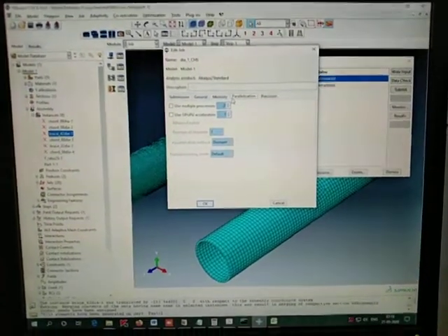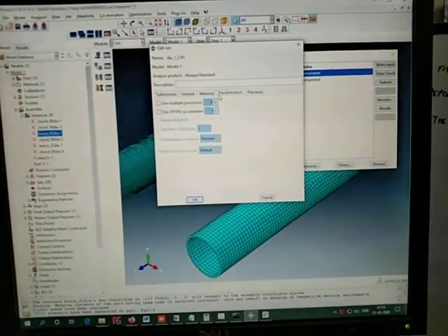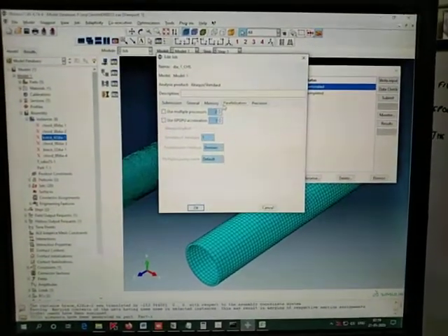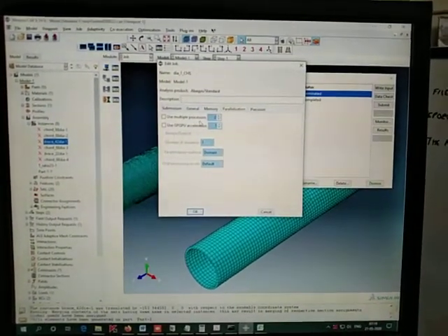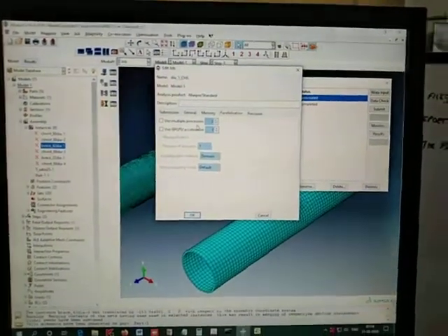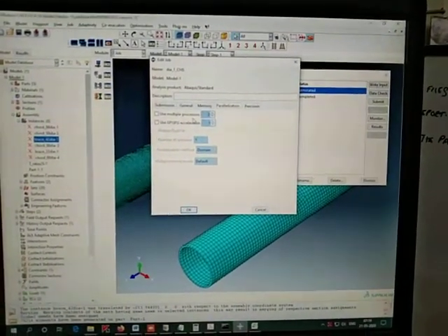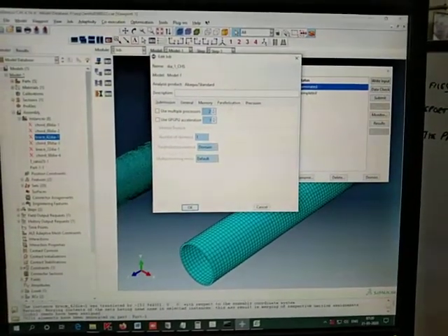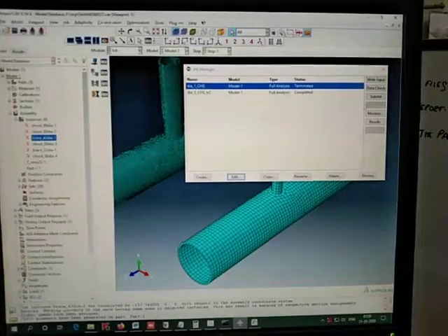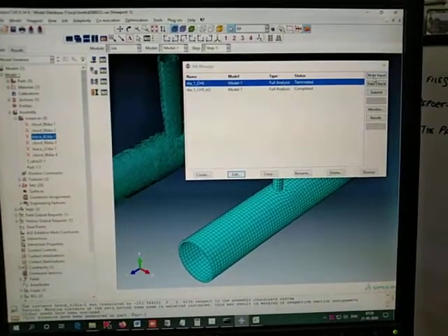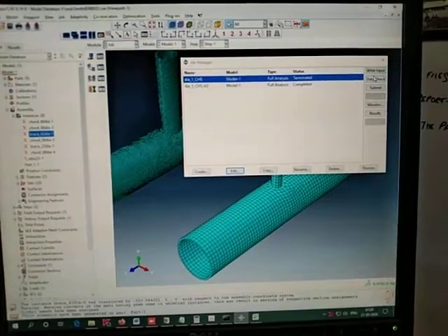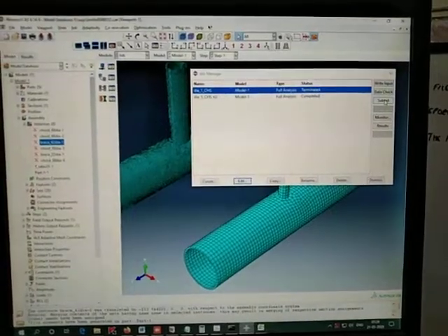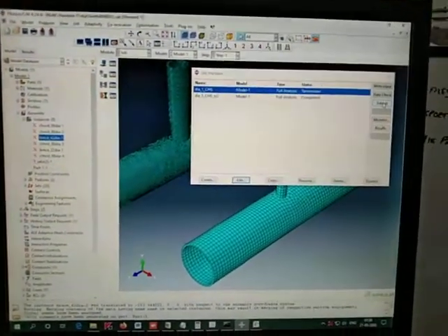And parallelization, when the mesh size is higher and the step time is also higher, when a finer mesh is used, generally opt for parallelization. And this parallelization should be less than the cores you have. For example, if you have 6 cores, go for a maximum of 4 cores. And GPU acceleration is not that efficient. And finally, if you give write input, it will only create the input file. Data check is to avoid the errors which we may have made initially, but these two commands are combined in the submit option, where we will have the results also.